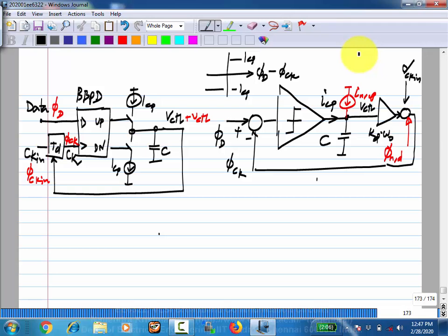Okay. So now this is a nonlinear model, and essentially if you are taking data conversion type circuits, you will see that this is some sort of first order delta sigma modulator type model, right? You have an integrator and a comparator in the loop. So you can use the nonlinear model itself to calculate some things, but you can't define transfer functions the way we did earlier.